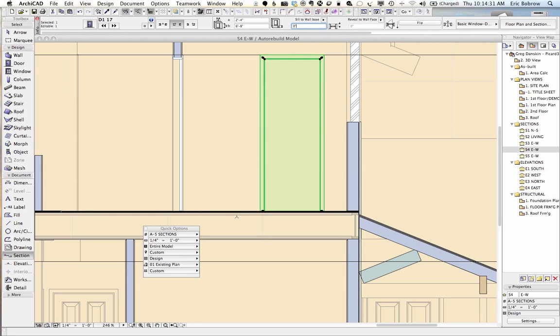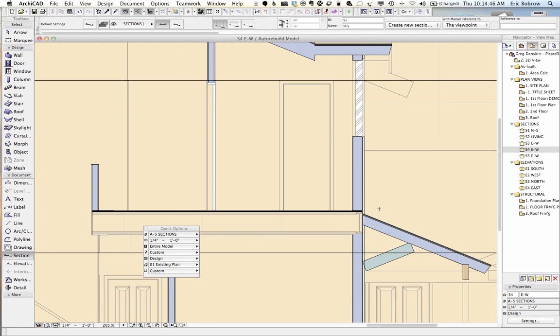If we were to move the wall down, then it's possible the door might need to be raised up so its threshold was above the carpet or above some finished floor. Yeah. So what I do basically is I leave it at 0, and then when I figure out what the floor finish is, then I boost the door up. Mm-hmm. Okay. Yeah. So I guess it sounds like having the wall start at the floor level and go up is better than stretching it down, like on the exterior wall.